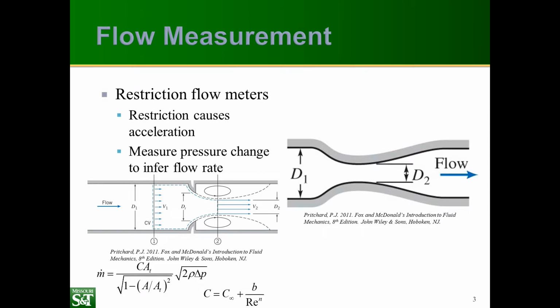The discharge coefficients for Venturi meters range from 0.98 to 0.995. So 0.99 is usually a good approximation for most conditions involving incompressible flows. Now, manufacturer-supplied calibrations can further improve the accuracy.